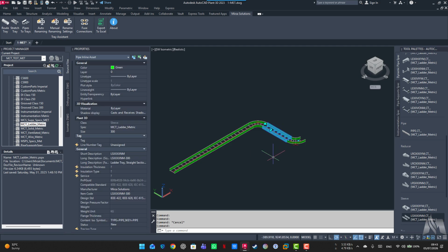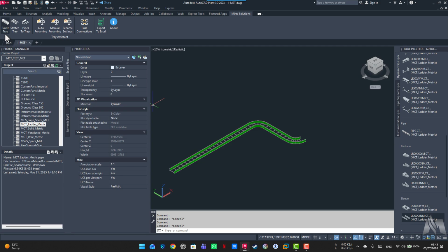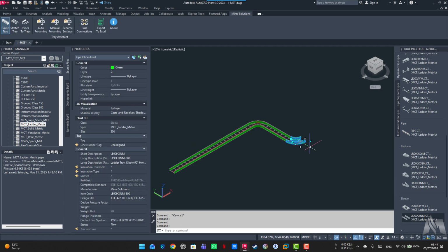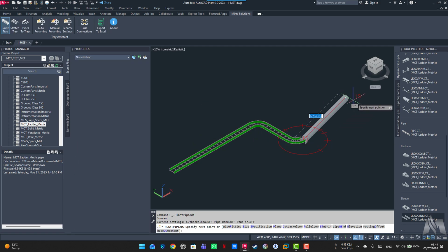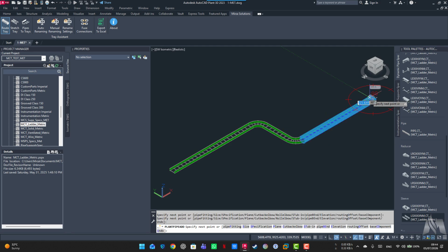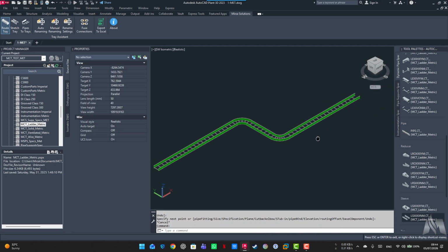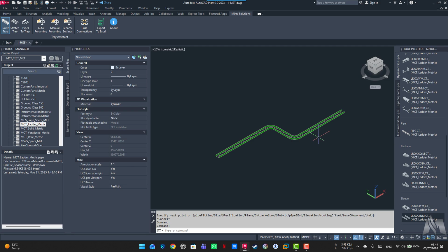And one more thing that I forgot to mention, when this is enabled, you can also click on the plus sign and draw a cable tray as well. For now, the auto routing is only for the straight section. Elbows and the other fittings are not included at the moment. I'm working on that, and we will be adding these features one by one in future.